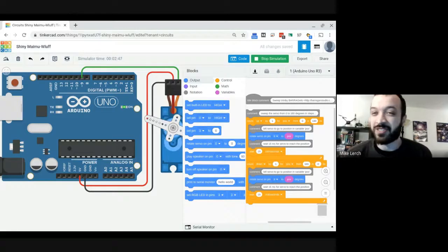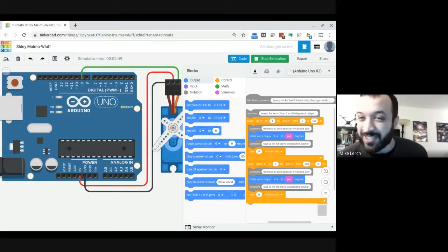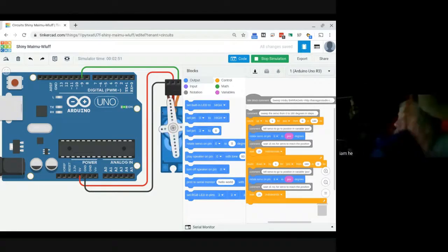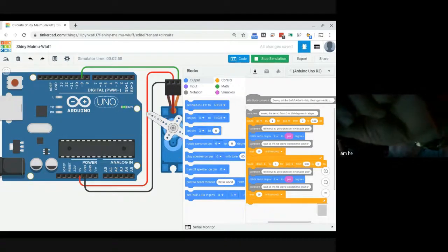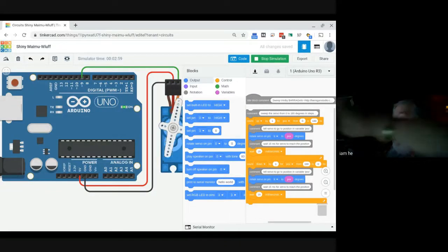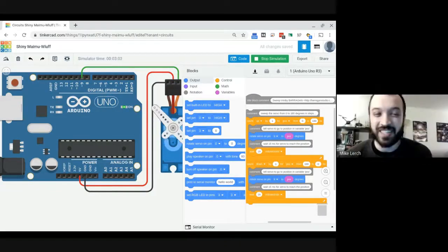And it looks like Rich is holding up a servo for us in the camera there. Yeah, and the Arduino and the microbit will power this directly, because this little one doesn't draw much power. So if you got one, it's going to be okay. Like the way that circuit shows, it'll do that. Small servos, yep, it'll spin freely just fine.